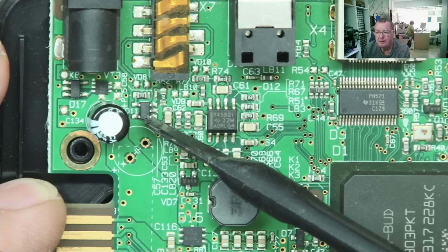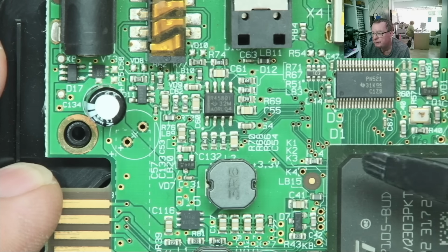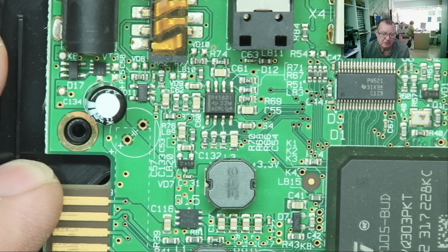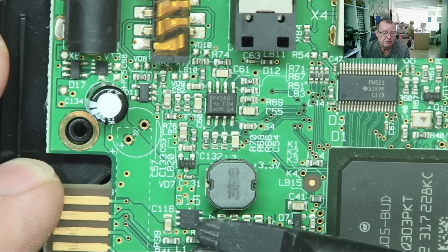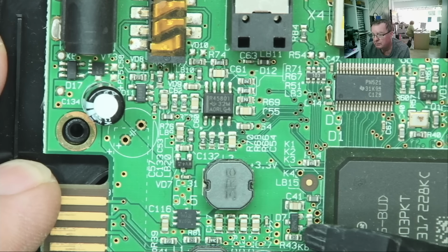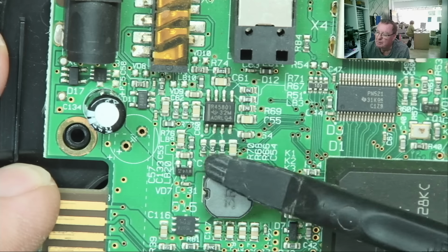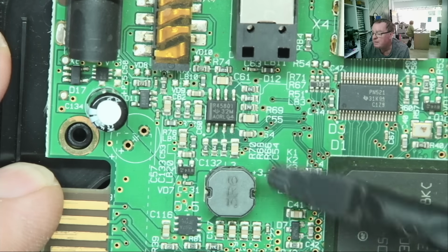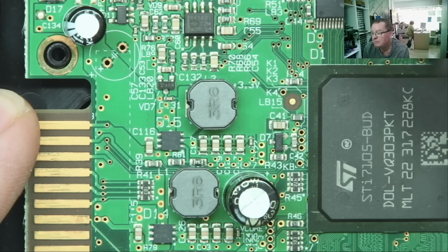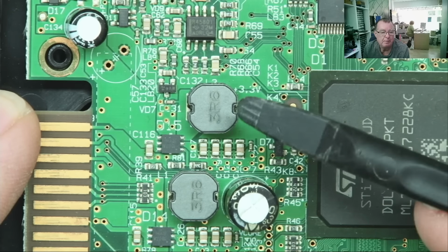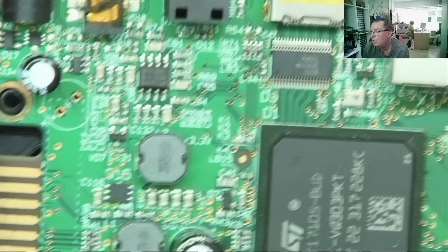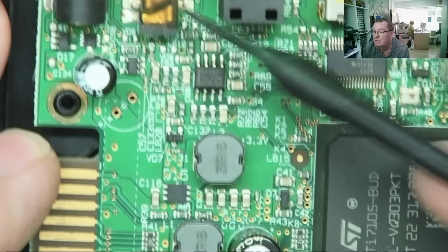The reason these fail is usually twofold. One, that there's some problem on the output of the DC to DC converter, so a short in the load will cause this to fail. So if you find these failing, you need to check to see if there's a short on the output. And if you look at the data sheet, you'll be able to figure out where the output is, or if you're more familiar with these circuits, if you measure from the coil to ground, that will also tell you where there's a short on the output. Bear in mind the device you're driving could be quite low resistance. It could only be a few ohms, depending on what is being powered. But these are quite a common failure point.